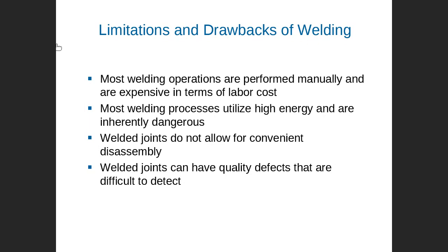Quality defect, because in welding, as I told you, it is a liquid mix. You melt the material in the welding zone, not all the material, and then allow solidification. Some defects could happen, like cavity and porosity. It's very similar to casting, and some casting defects are similar to welding defects.